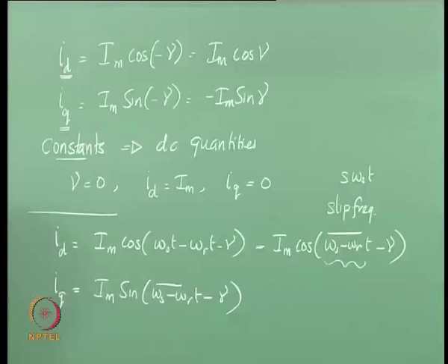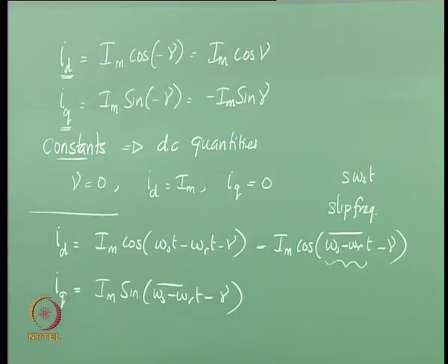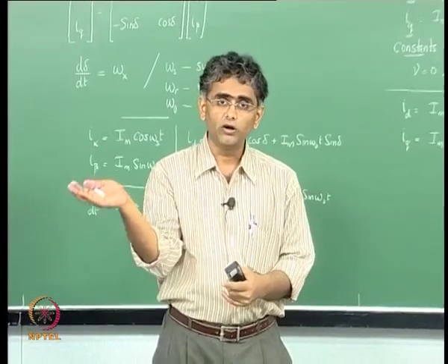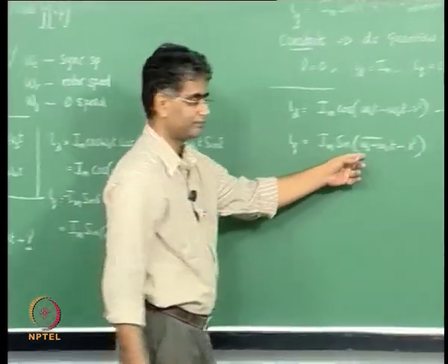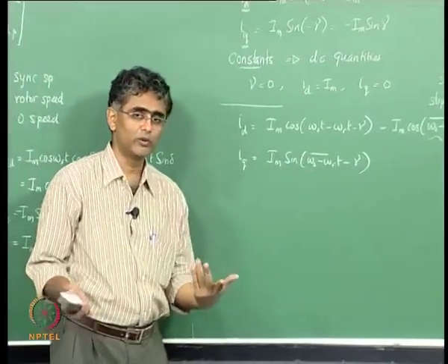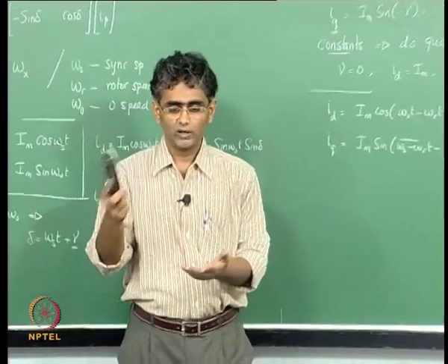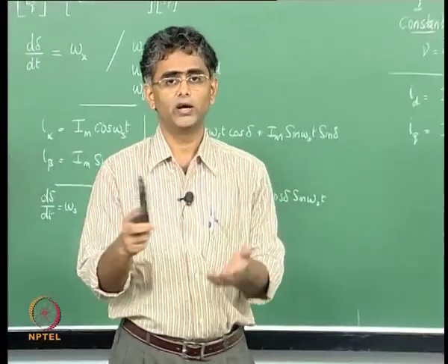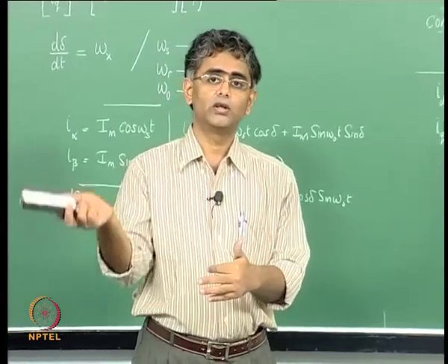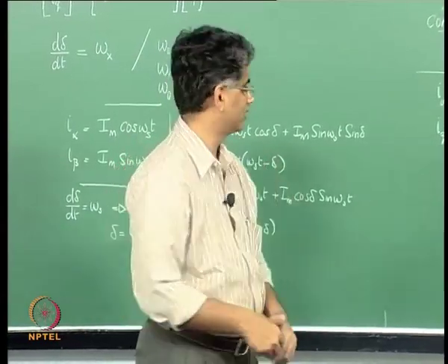That means anything that you see from the rotor, all the mmf's that are there in the air gap, all appear to be rotating at slip frequency. The actual mmf is rotating at synchronous speed, but sitting on the rotor you are also rotating at rotor speed, and therefore with respect to you the mmf's appear to rotate at slip frequency.